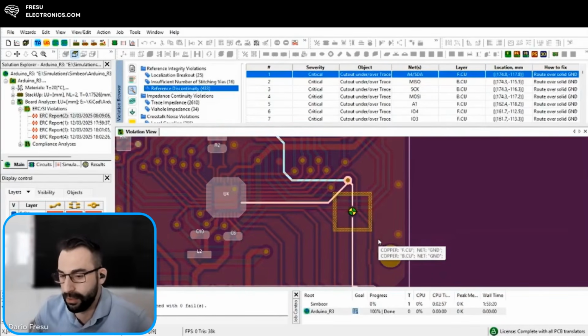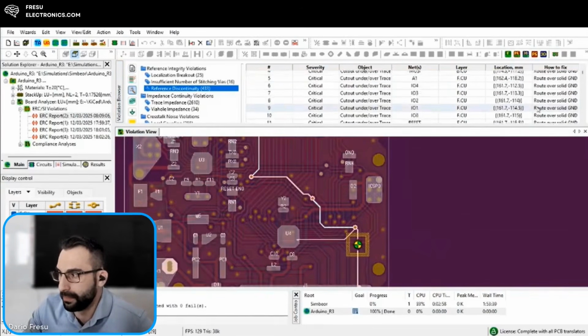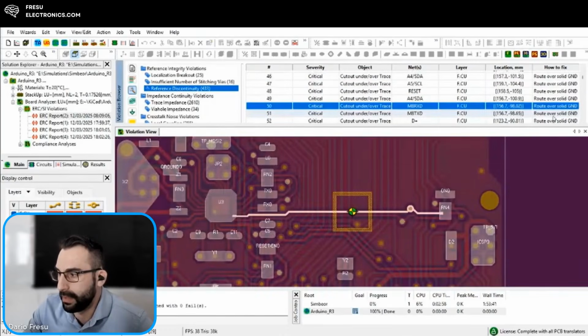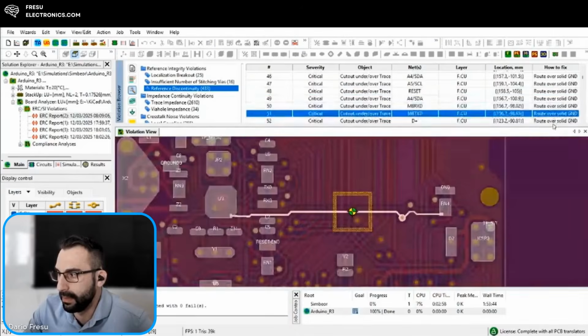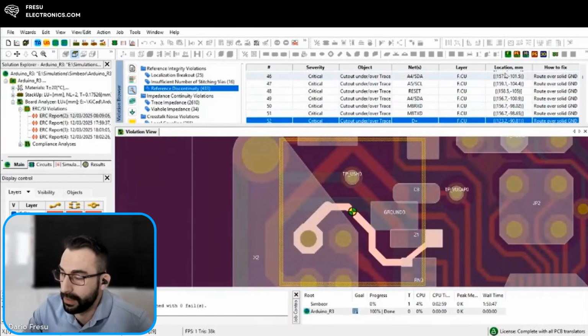And we'll also ensure that you're not going to spend thousands of dollars when you go and do the EMC test and you fail, because this is a guarantee for failure. And so it's still the cheapest possible stackup. Okay, so you see in here, it tells you to route this signal because there is no reference adjacent to it.